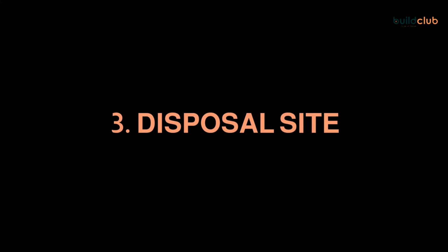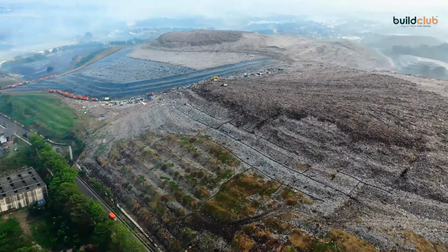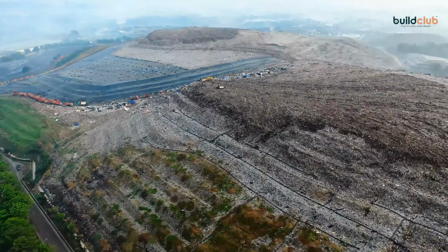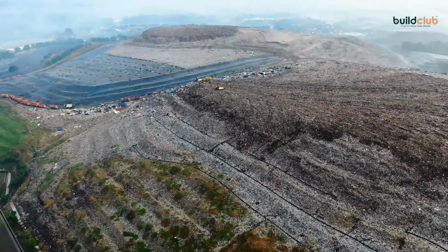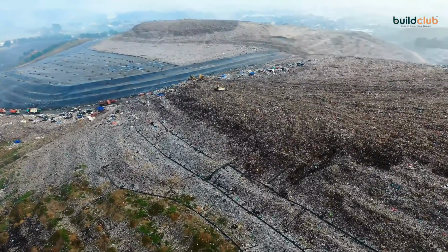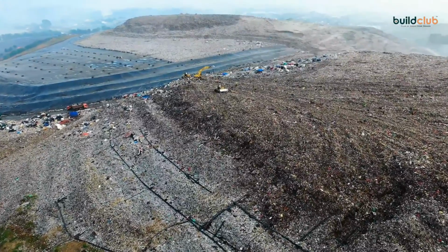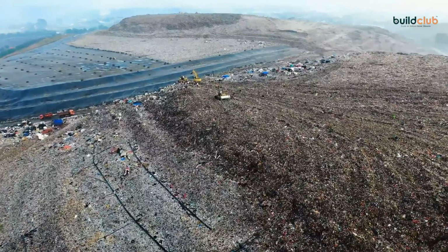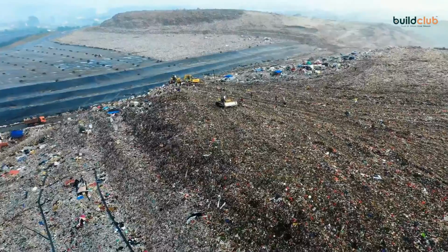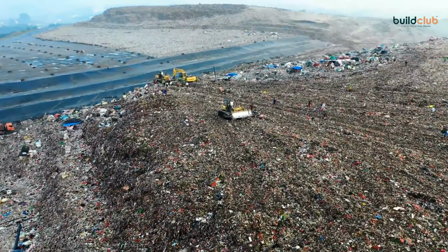Next in the line is a disposal site, previously a landfill or dump yard, you may say. It's the worst kind of site in comparison to the other three types. You may find such sites rarely though. Sometimes, certain low-lying areas are designated space for landfill. Once it fills up to a standard ideal level of the nearby geographical terrain, it is backfilled with soil and prepared for real estate plotting. Certain low-lying landfills have a depth of above 100 meters.